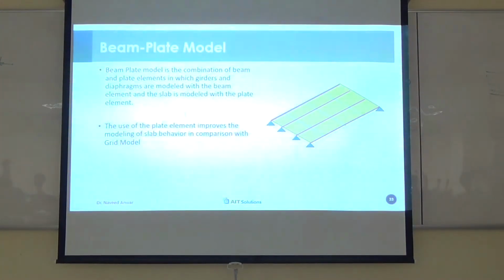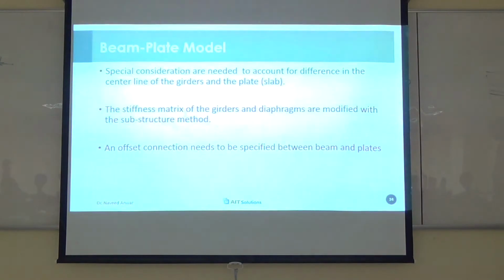Beam plate model, instead of the grid, we fill it with plate. But again, not so good, because it does not have in-plane behavior. Same problem that we talked about before: it has bending, but it's not in-plane. So it doesn't capture the in-plane response of the deck. So again, not so great anymore.